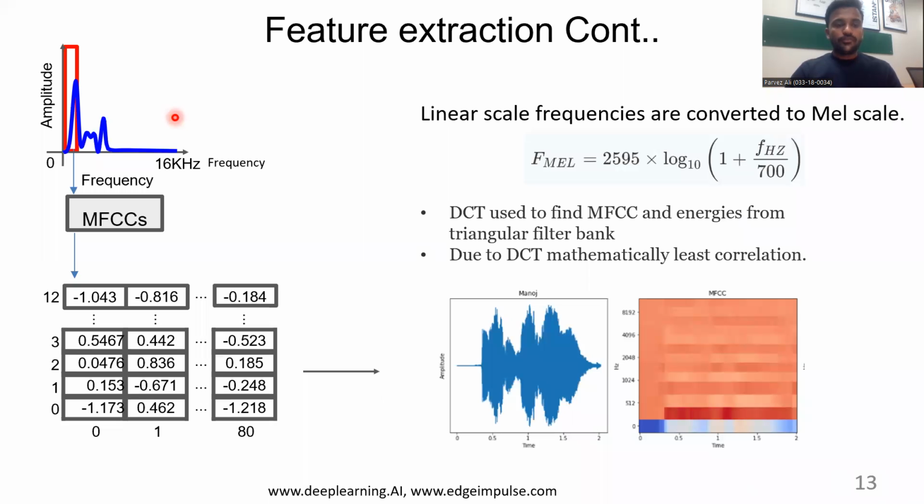And when we have a frequency domain signal and we use this mel scale, so we have to also convert a frequency domain signal into mel scale, then we get this kind of a matrix, and the width of the matrix depends on the filters that you use. There are a total of 31 filters in mel frequency cepstral coefficients. We have used 13 filters, so we get 13 columns in our feature set, and this feature set looks like this when we visualize it as a picture. So it looks like this image, which is different for each speaker.